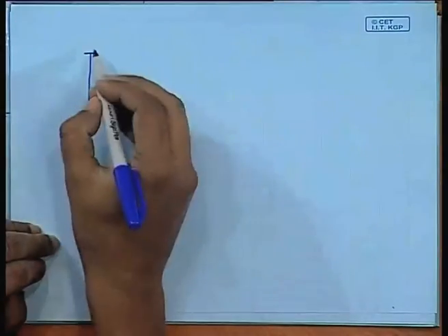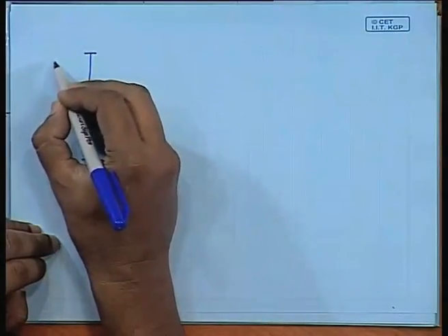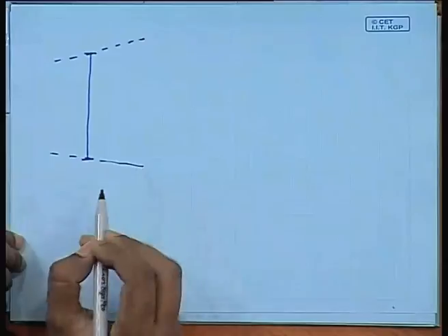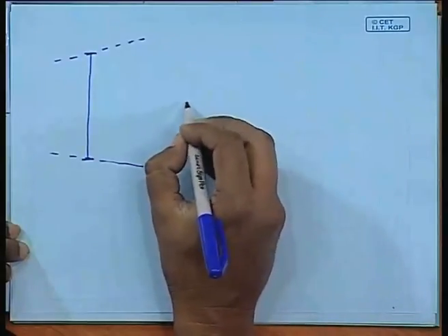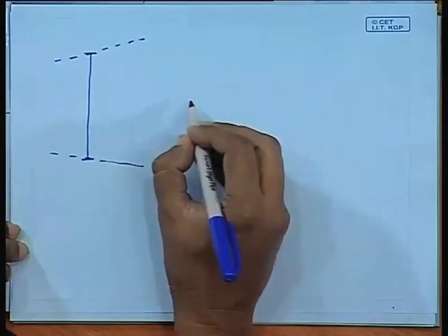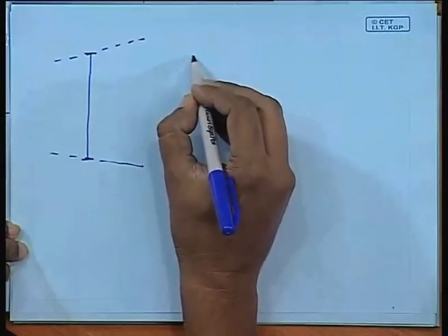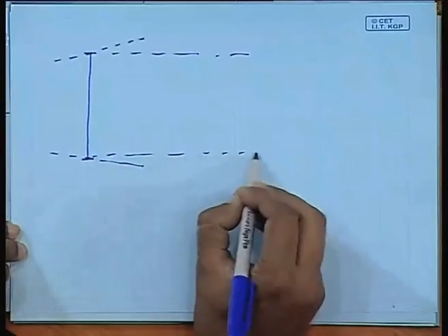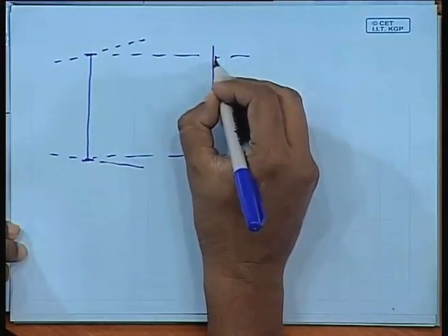A cross section of the plume along its line of travel. So the plume is traveling, as we have already discussed, taking a shape like this. Let me consider that we are taking an imaginary cross section inside this. What we observe under this Gaussian plume distribution is that if you make a projection here, the distribution is completely normal.